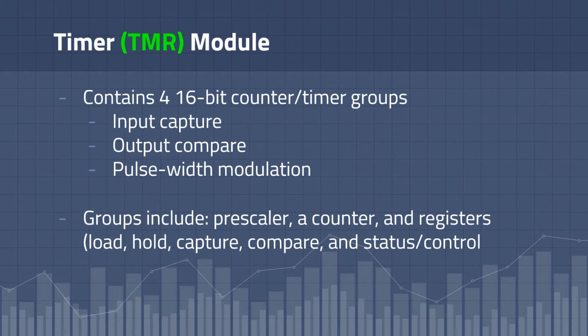The timer module can also handle 3 kinds of interrupts. The first is a timer compare interrupt. This happens when a match occurs. The second interrupt is a timer overflow. This happens when a counter exceeds its maximum preset value. The third and final interrupt is the timer input edge, which happens when the input signals transition from one to another.